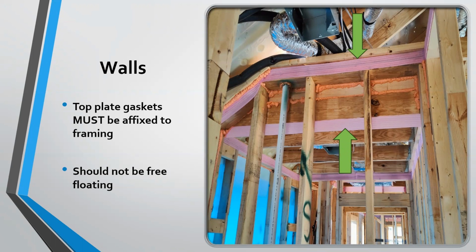When the sheetrock gets installed, yes, it will lay over the top of that. The only place it's air sealed are the vertical studs. There is no air sealing happening because there's nothing to back up the gasket. So without blocking here, the gasket is ineffective in sealing the front of this joint, and attic air will make its way through there. With an IR camera, you will be able to see that.